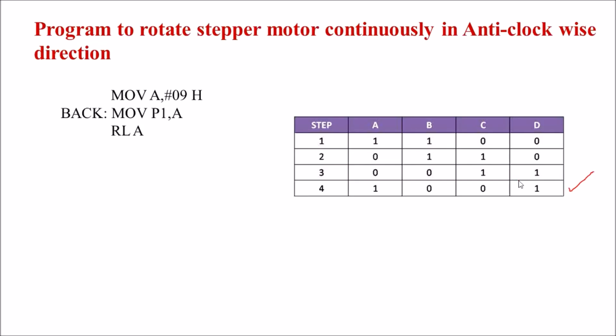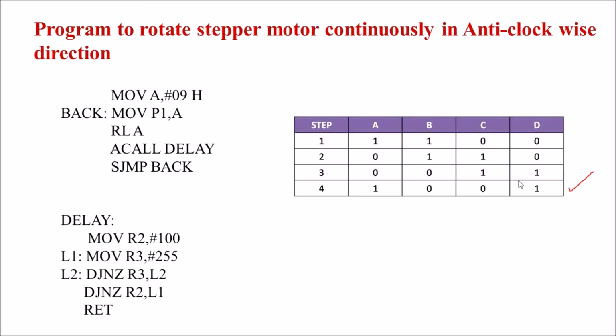We'll rotate the contents of the accumulator left by 1 bit. We'll call a delay and we'll execute this program continuously. Again for delay we can write a simple delay program.